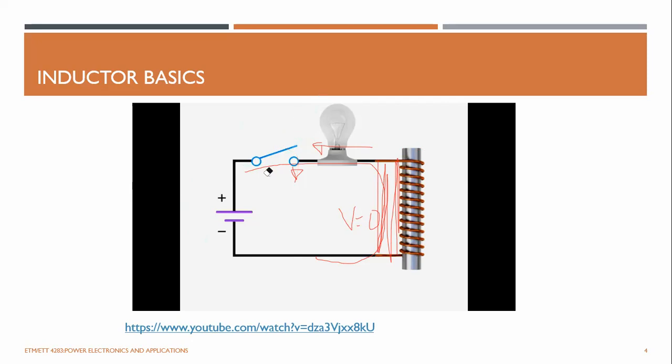So these are the very basics of the inductor. Most people who are working with these sometimes forget this concept, and sometimes they forget what freewheeling diodes are, so they end up destroying their circuits. So always remember to follow your fundamentals and basics. That will help you to work without issues.